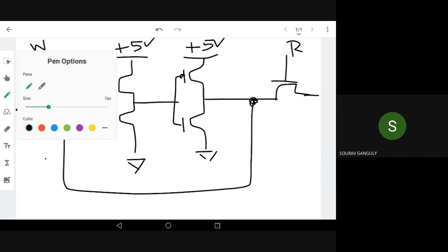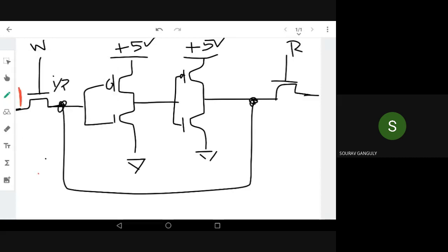So how to write something? I'll make some bit high and I'll make W equal to 1. So this high voltage goes to the input of the inverter and becomes high, from 0 becomes 5. Now 1 is charged. So this 1 bit is stored in the SRAM cell. Now for reading, I need to put R equal to 1. So this charge, this voltage, is transferred to the output. And at the output, I need a sense amplifier, sensing whether the voltage is high or low. So I sense what bit is stored, and I take this to the output. Each of these bits is stored like this in an SRAM cell.